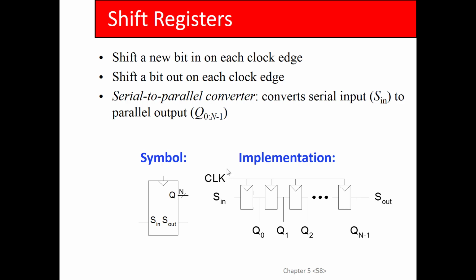The purpose of this, as the book notes, is that you can make a serial to parallel converter of this. So if you can imagine, if you have 16 of these connected, in 16 cycles you feed it. You can load these up by feeding 1 bit at a time serially, and then all of those 16 bits will be presented here that could be read out in parallel. You guys with me?